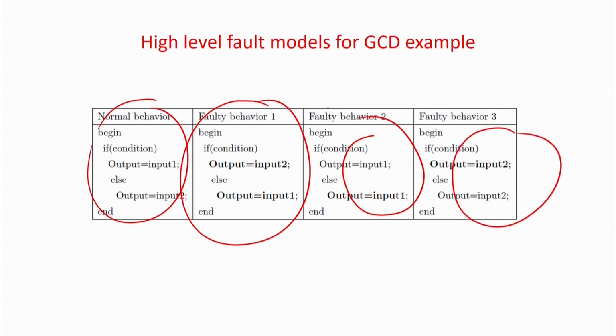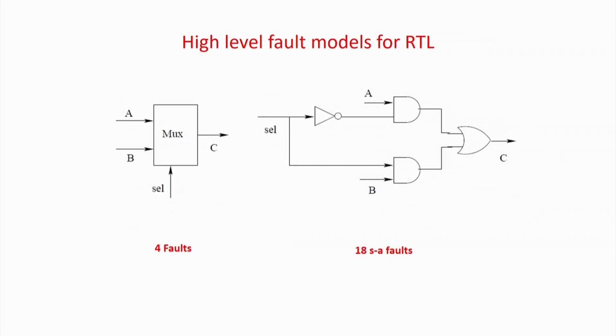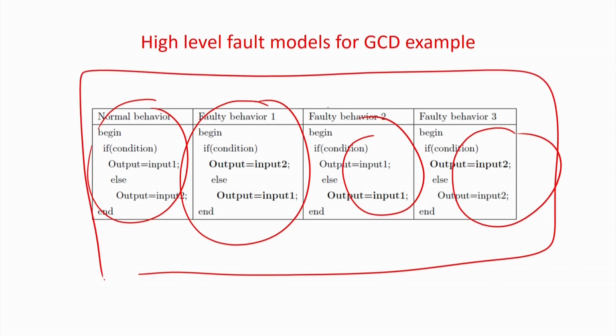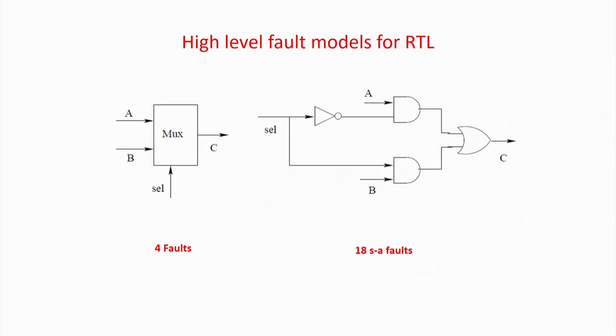So basically they are the fault models which are very much appropriate for a multiplexer. So people have found out that if you test for all these faults in a multiplexer, the correlation is very high with a gate level model. So what we do, one is the swapping and one is the constant input and one is the constant output. That is, one A will always go, other B will always go, and the other is there will be a swapping. Those are the 3 fault models basically, and one is the normal. So I should not call it actually 4, basically 3. One is actually the normal condition.